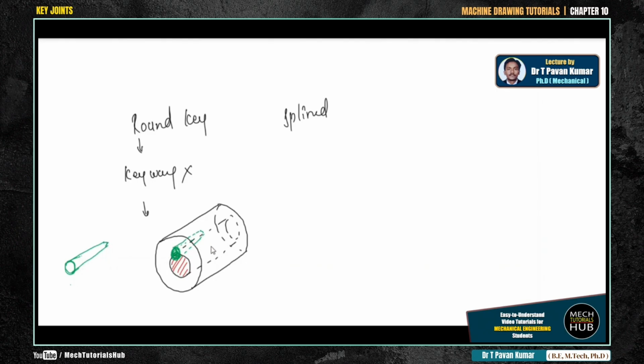This is completely different. Till now what we have seen is that a keyway is provided, and keys are fabricated or manufactured and pulled inside the hub and the shaft. Now the shaft is inserted, then drilling is performed between the shaft and the hub, and a separate round key is developed, which is heated or pulled inside these two elements. That is the difference.